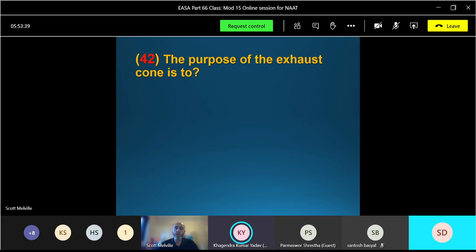No, not quite. Give you a clue. What shape does it make against the exhaust wall? So you get pointy... Divergent. Divergent, yeah. So it's a divergent shape. It's going to slow the gas down. That will reduce what? Reduced velocity. Yes, reduce the velocity.